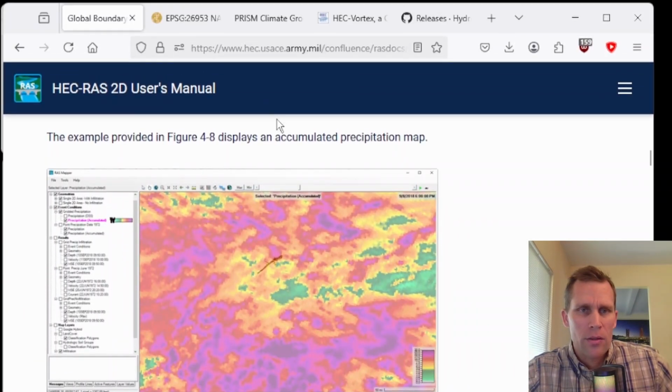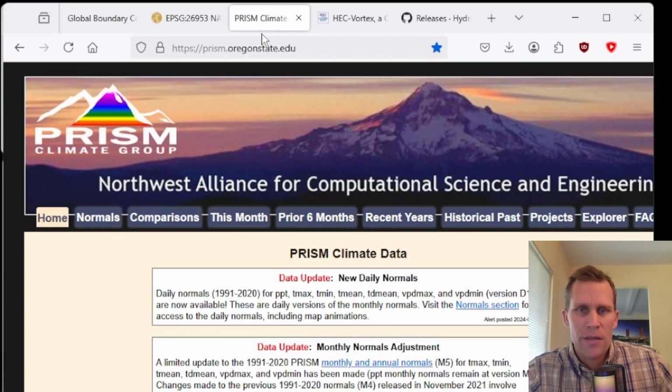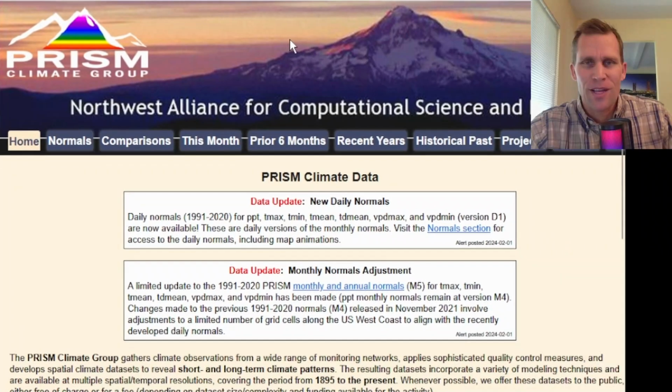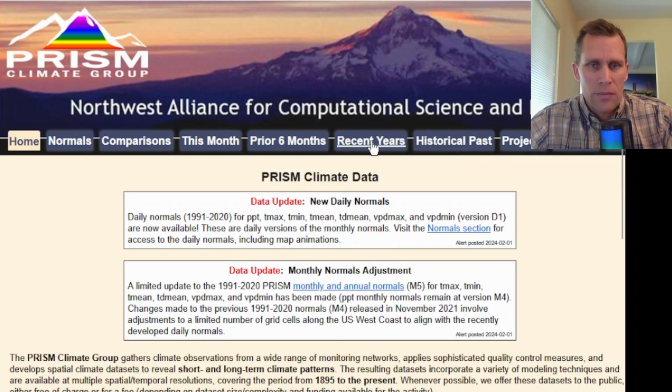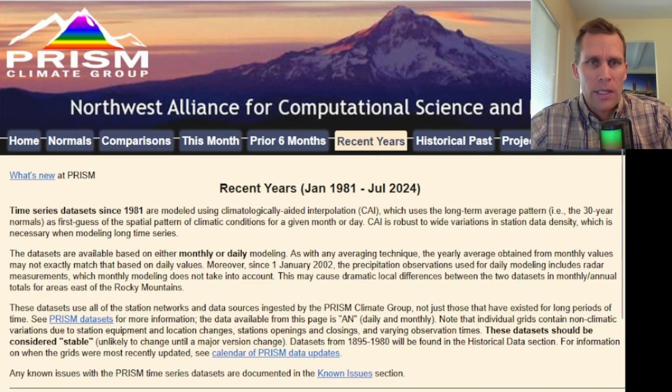All right, while that's downloading, I'm going to come over here to PRISM data. There's lots of information and sources online for precipitation data. PRISM's been one of my go-to sources for matching correct volume, at least, but it has continental United States precipitation data on a daily time step. So let's go ahead and use that. I'm going to click on, let's see, recent years, and I'll leave a link to this PRISM website in the description of the video as well.